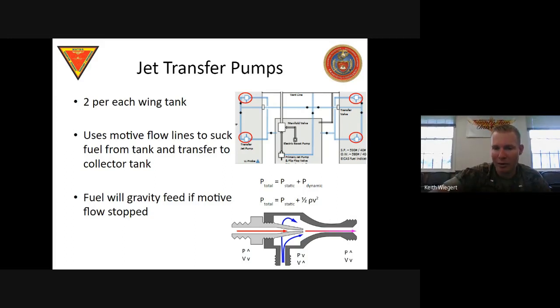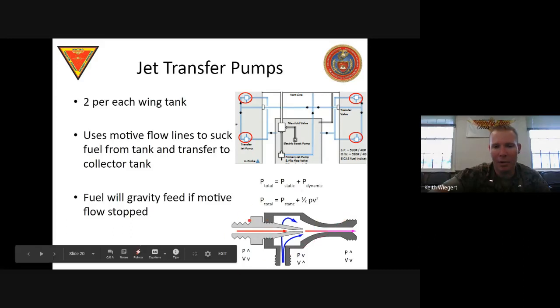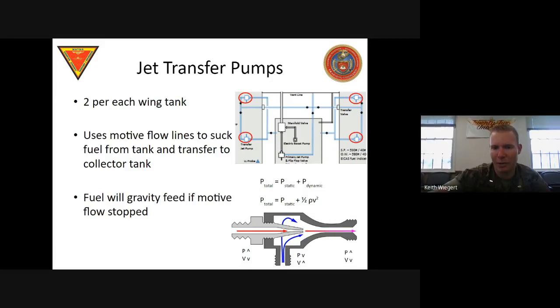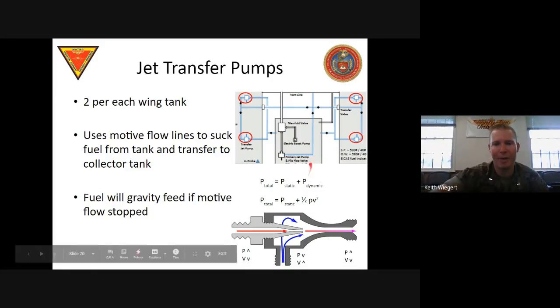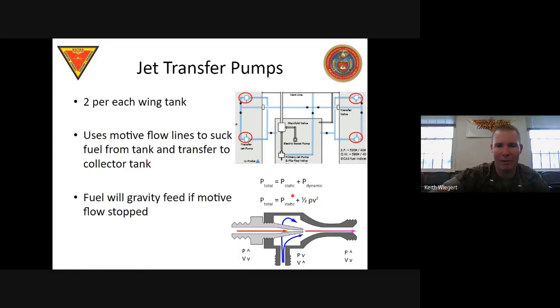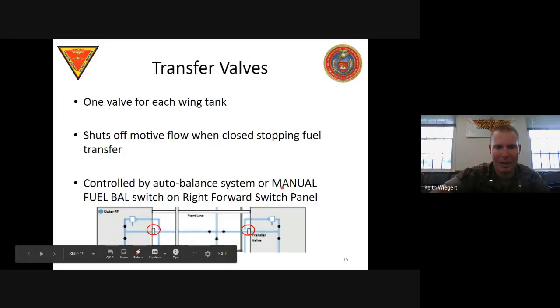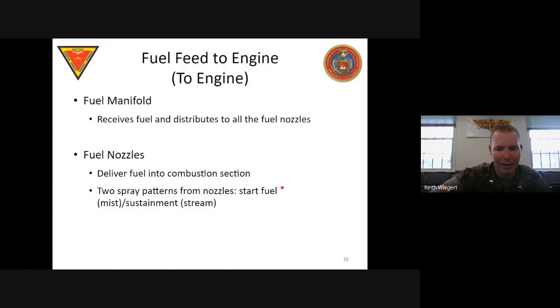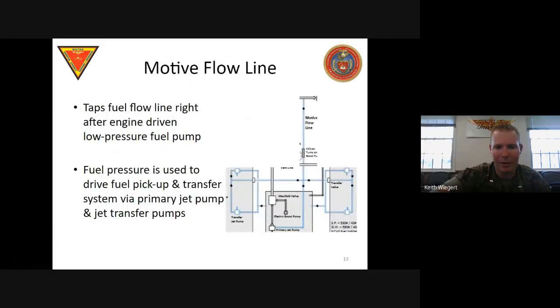Now, if you don't know anything, this is all based on Bernoulli's principle, right? Remember, it's the same principle that's creating our lift as well. So if you can throw out Bernoulli's principle and just say the motive flow system works based on Bernoulli's principle, cool. And then if you say that all of the jet pumps are little venturis that use Bernoulli's principle to create motive flow, your instructor is going to buy that. That's how this works, okay? So if you say Bernoulli and venturi anytime you're explaining this, all right, cool, you're going to be able to explain it fine. That's how this works technically, though. I like getting technical with this stuff. I don't know, probably a good thing or a bad thing. Who knows?